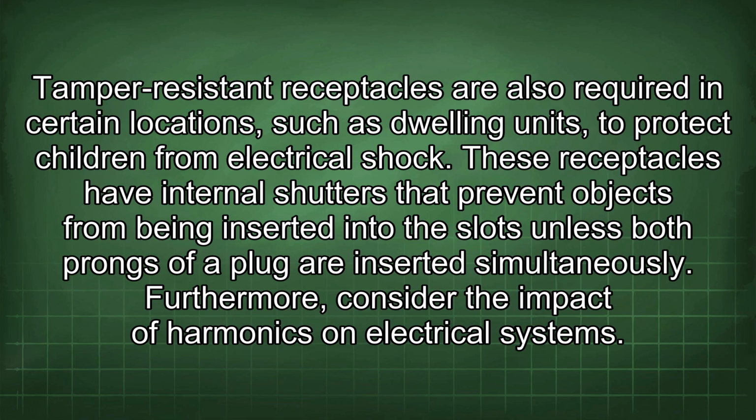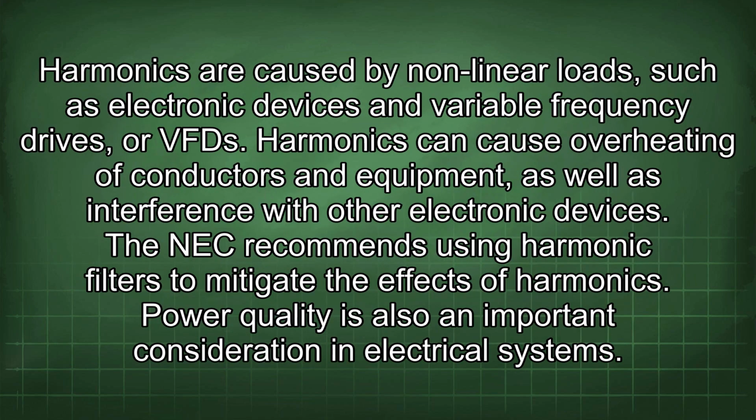Furthermore, consider the impact of harmonics on electrical systems. Harmonics are caused by nonlinear loads such as electronic devices and variable frequency drives, or VFDs. Harmonics can cause overheating of conductors and equipment, as well as interference with other electronic devices. The NEC recommends using harmonic filters to mitigate the effects of harmonics.